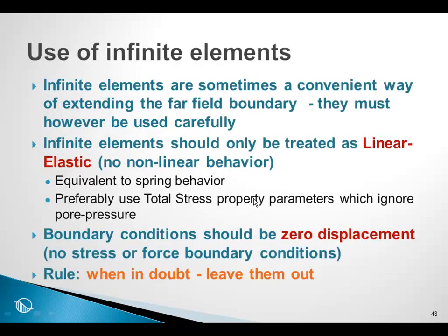and in this example we'll show how these functions can be defined in SIGMA/W. A few comments then about the use of infinite elements. Infinite elements are sometimes a convenient way of extending the far field boundary of a problem, and in SIGMA/W it is the left and right far field boundaries. These elements, while they can be very useful, they must be used with considerable care. Generally, infinite elements should only be treated as linear elastic. That is to say that we should not assign nonlinear behavior to infinite elements.